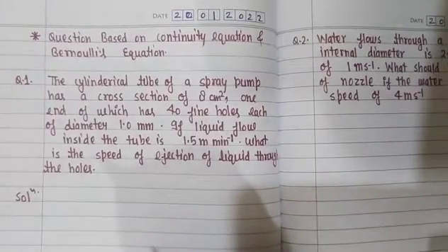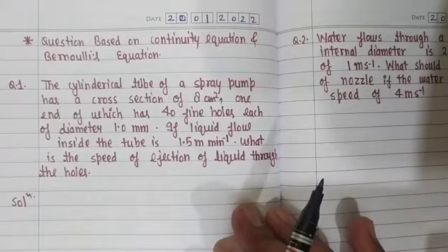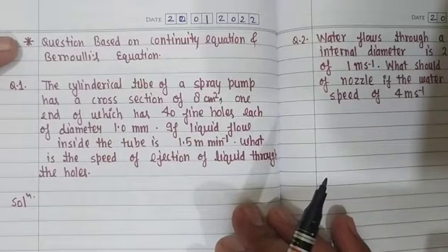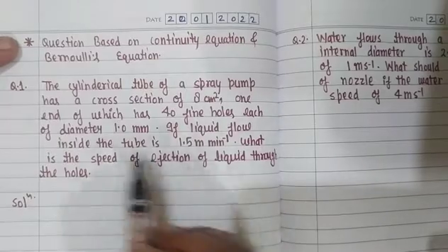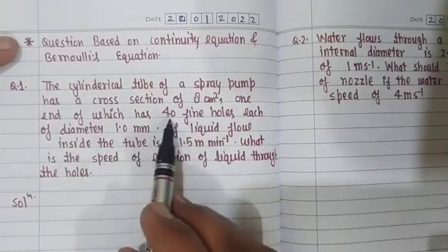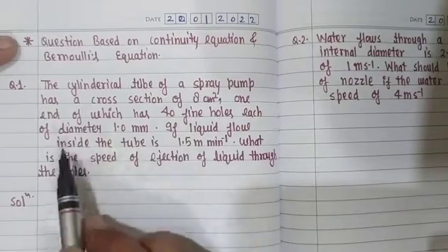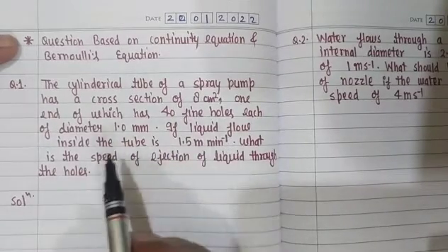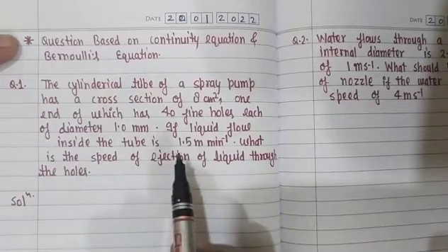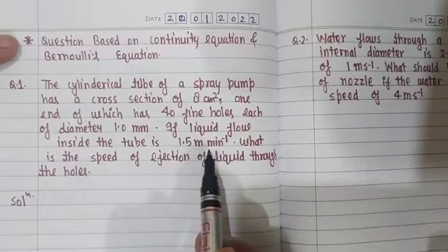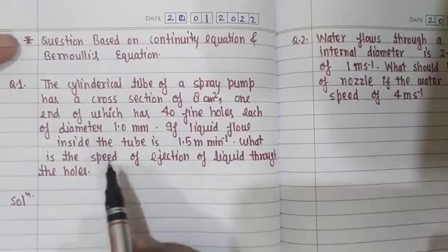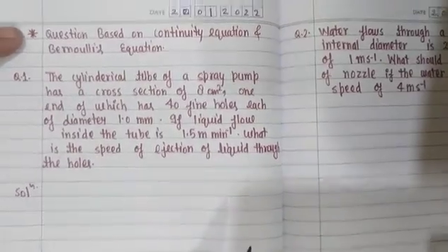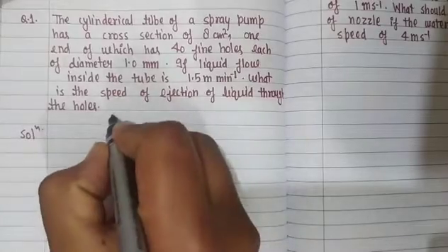So here the first question is, the cylindrical tube of a spray pump has a cross section of 8 centimeter square, one end of which has 40 fine holes, each of diameter 1 millimeter. If liquid flow inside the tube is 1.5 meter per minute, what is the speed of ejection of liquid through the holes? So let us consider we have a cylindrical tube here,